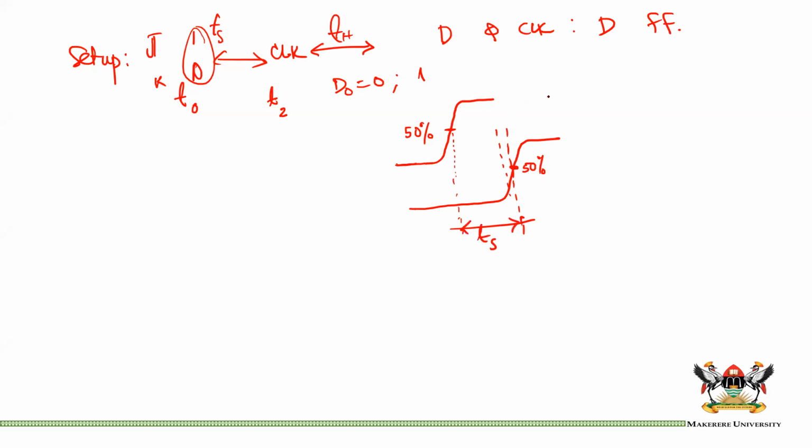And once again, maybe this is the clock. But you should keep this within that period once the clock transitions, but we need to measure it at this point. So from here, you need to keep this in this state for a bit more time, which is your holding time.